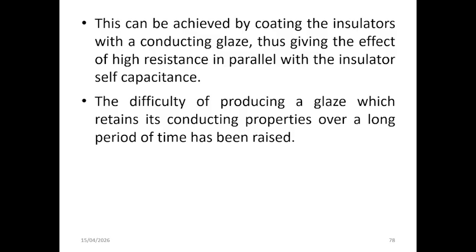However, a major challenge here is maintaining the long-term stability of the conducting glass. Over time, environmental factors such as weather, pollution, and aging can degrade its conductive properties, and it will make it less effective at reducing the shunt capacitance. So due to this reliability issue, the method is not widely adopted in practice in comparison to other methods.